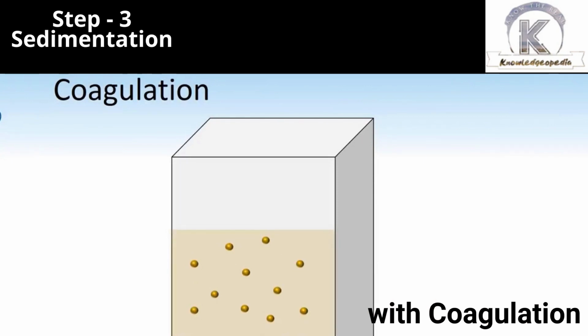The overflown water after primary sedimentation further goes to the second level of the sedimentation process, which is flocculation, in the flocculation tank. The sludge particles which have not yet been able to settle down in the primary sedimentation tanks are removed under the process of flocculation or coagulation.